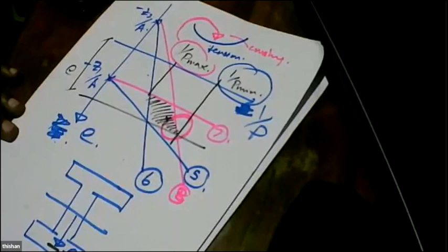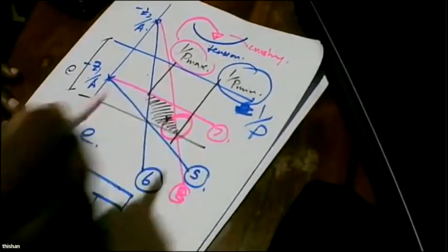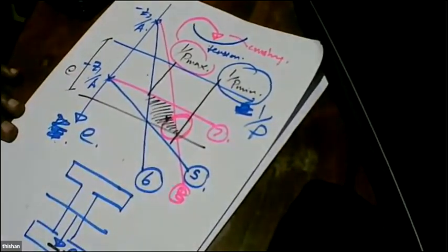It should be as low as possible. So that's the reason why, when you draw this diagram, not using equations, you can straight away say in which region we should be selecting the pre-stressing force. And we should select the pre-stressing force as low as possible,